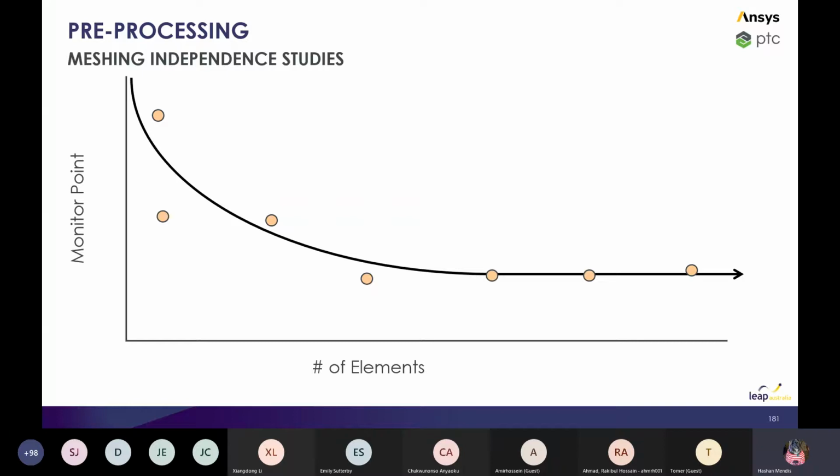This stuff can get pretty difficult sometimes. So again, if you've run a couple of jobs and you're running some meshes and it's not quite giving you the results that you're after, do come let us know. Sometimes what can happen is that when you've got finer and finer meshes, instead of running a steady state, you can start to pick up these transient flow features as well. So just making the mesh finer isn't necessarily the correct answer.